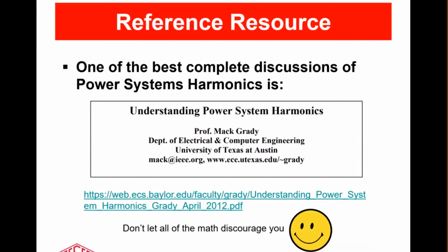So that's one of the reasons why there's an increasing push to use VA metering, or at least properly, consistently computed power factors based on consistently computed VA, in order to have a billing methodology that better represents the impact of the harmonic customer on the utility. Sorry for being so long-winded there.